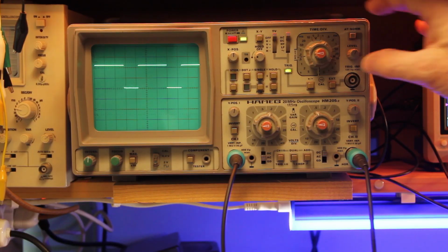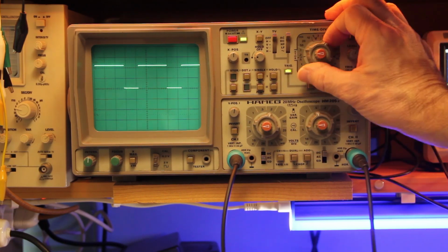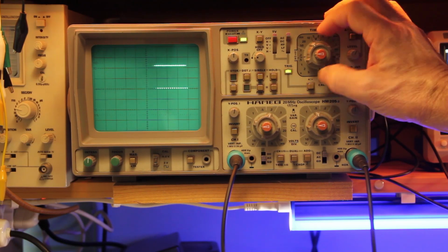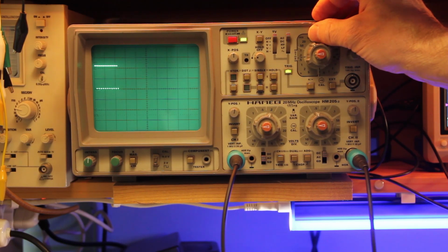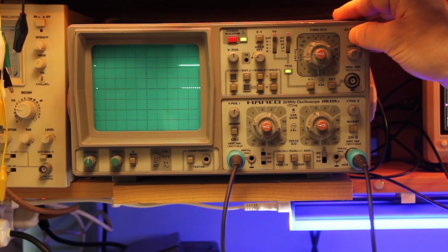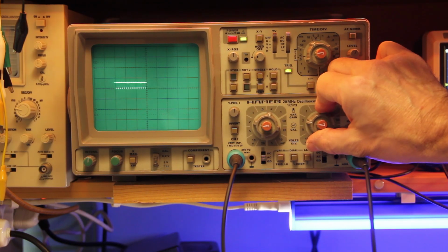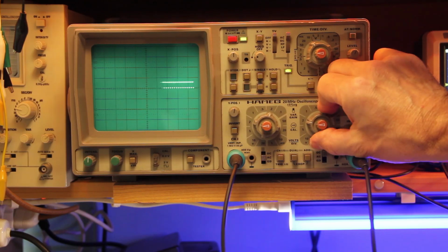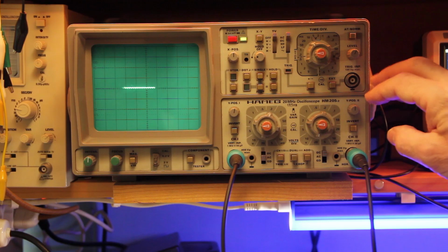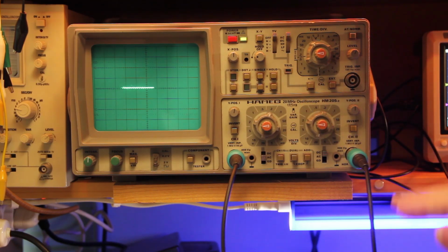So when you have no idea of what you are going to measure, the default adjustments should be to put the time division to a pretty low frequency, but not too low, and set the trigger to automatic, and reduce the sensitivity and increase the attenuation to maximum attenuation, so you are sure that the voltage that reaches the instrument is attenuated